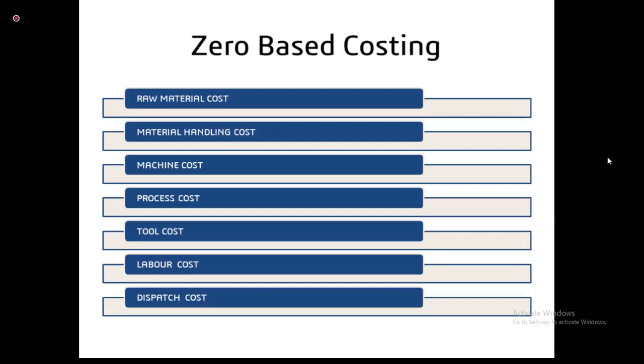Whenever you want to optimize the process planning of the component, it means that you have to go through every hierarchy of the operations of the component. If you can navigate the hierarchy of the operations, you can optimize the process of the component. Once you optimize the process, it will reduce the cycle time, it will reduce the machining time, and ultimately it will reduce the cost of the component. So it is very important that every manufacturing company should have a clean process sheet approach.